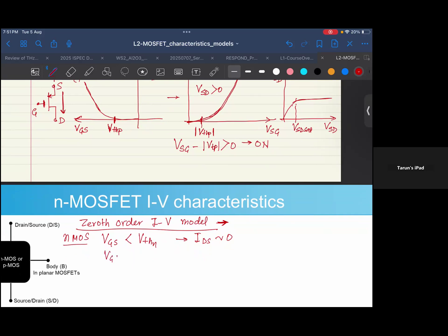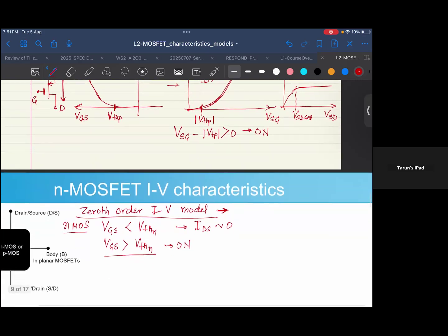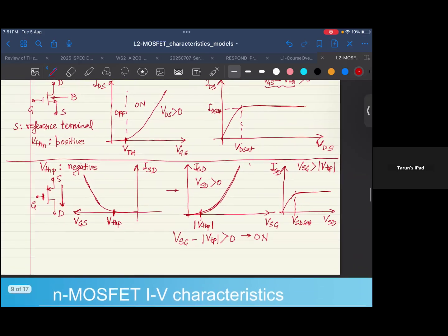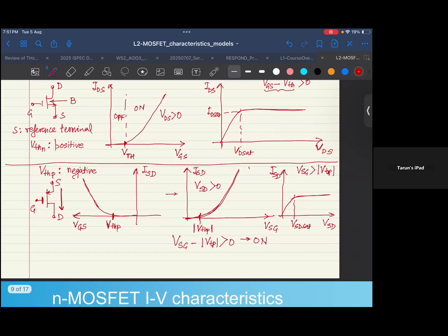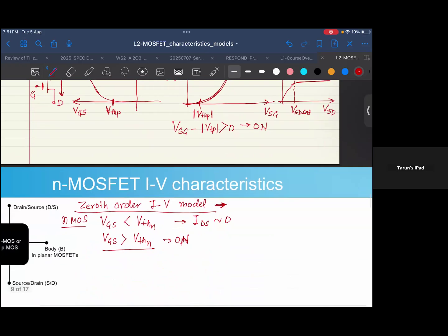Now, the model which we are trying to form is for the condition when the transistor is on, right? If the transistor is on, we saw that there are two regions where this is dependent, right? First we see the observation that when it's above VGS minus VT, your ID increases with some polynomial function of VDS, right?